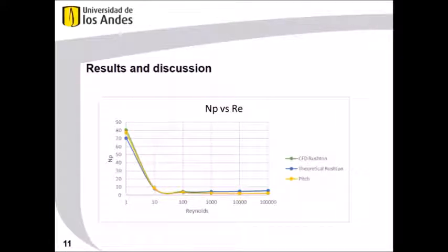Additionally, the power number depends on the geometry of the turbine. Notwithstanding the same dimensions and parameters for the turbines, at a specific Reynolds number, this value is different for each one. In the laminar region, the power number obtained with the Rushton is slightly superior to the pitched turbine. Otherwise, in the transition section, this value is similar for both impellers. Lastly, the power number is higher for the pitched than the Rushton turbine in the turbulent regime, which implies that more energy is required for mixing with the impeller design in this section.